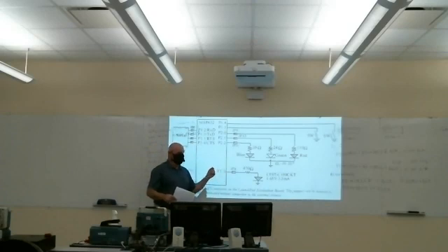And then we have to write a binary 1 to that particular pin. I haven't showed you how to do that yet. I've only showed you how to actually select the function. But in order to write a logic 1 there, we just write a 1 to another address, much like we set up the selection registers. Okay. That will turn the LED on. And I'll write a 0 to that bit in a particular register, and that'll turn it off.